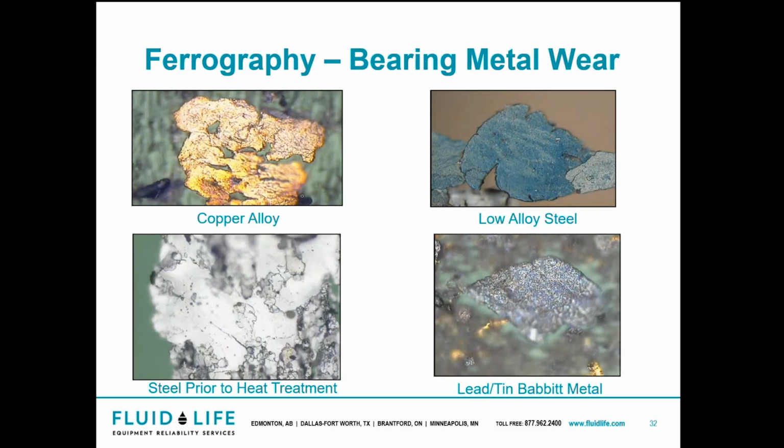Bearing metal wear, and I just mean this in a general sense, this is fatigue wear. As equipment gets old and broken, just like we do, things start to fatigue and wear out. You get a stress concentration on, say, bearing races or a hard particle in there. Every time a roller element or a part of a bearing runs over that same spot over and over and over, it's going to generate micro cracks. Not even SEM necessarily will see it. A high powered SEM might see it, but you're going to generate these cracks, and every time it's going to propagate that crack more and more until eventually a piece of metal flakes off.